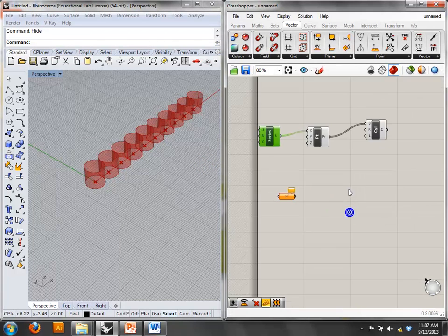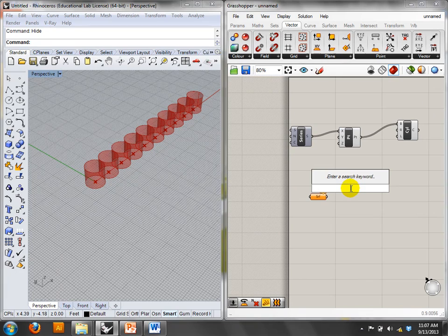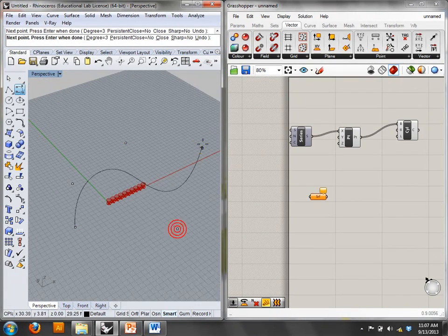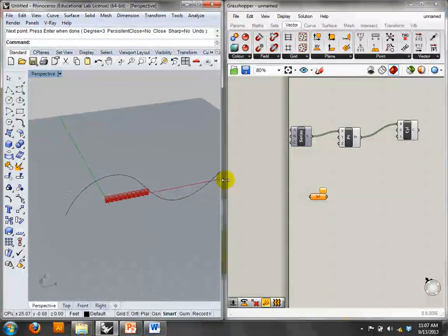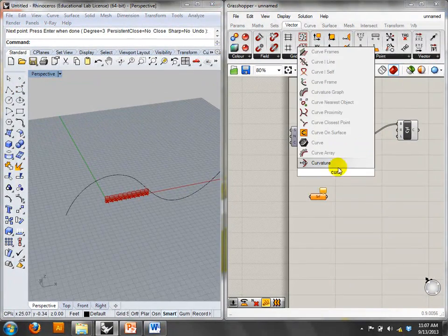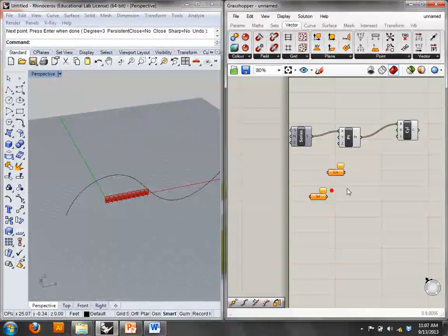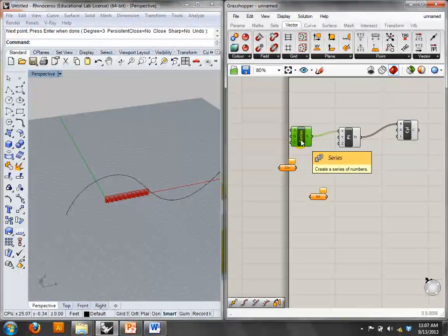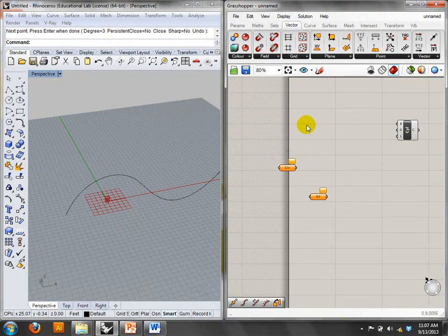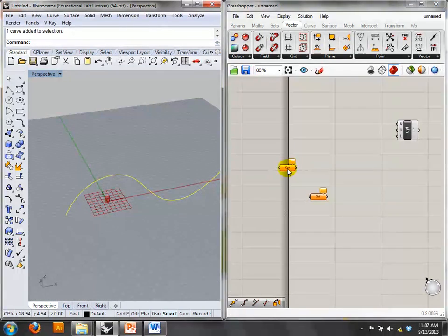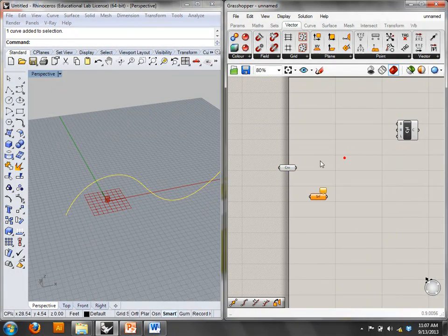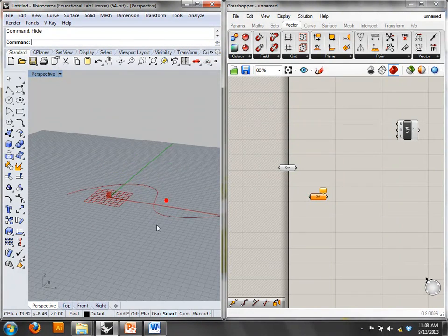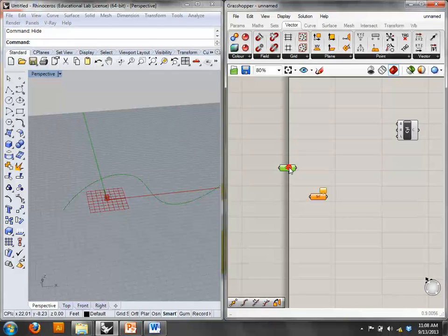Then some of the things I showed you were that I could make a curve. I'm just going to draw some kind of random silly curve here. And I can reference that curve, so instead of using numbers to make points, I can reference this curve. Now it's in the system, and I can even hide this now. It exists in Grasshopper as a state. It turns green.